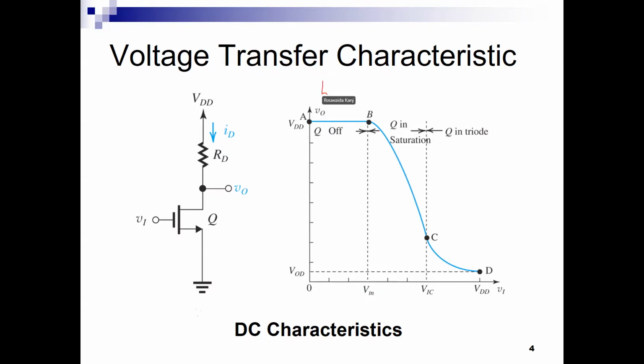It has two low gain regions, this one and this one, and it has a high gain region. Somebody may wonder, I see this as a common source amplifier. What happened? When we used to operate this circuit as a common source amplifier, we used to send a signal Vn as a function of time with some DC bias, let us say to the point Q here, say VDD over 2, and around VDD over 2 we would send a little sinusoid.